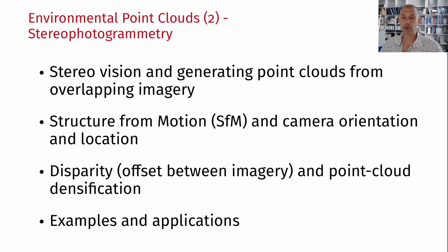I also would like to point out that there is a second part of this class that focuses on stereophotogrammetry, and there we talk about stereo vision and generating point clouds from overlapping imagery. That is a fundamentally different way of generating point clouds, but has a wide range of applications. So we are going to talk about some structure for motion and camera orientation and location problems.